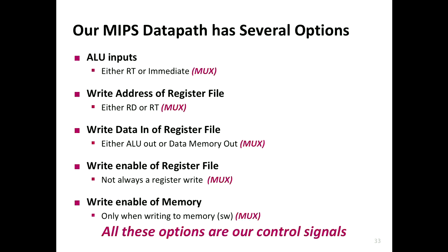And all of them are muxes, right? They're all simple multiplexers. You can have a control signal value that actually chooses between a register value and an immediate value, or here, whether you want to feed in the data coming in as a result of the ALU or directly from the memory. So these are all simple control signal values that need to be implemented.